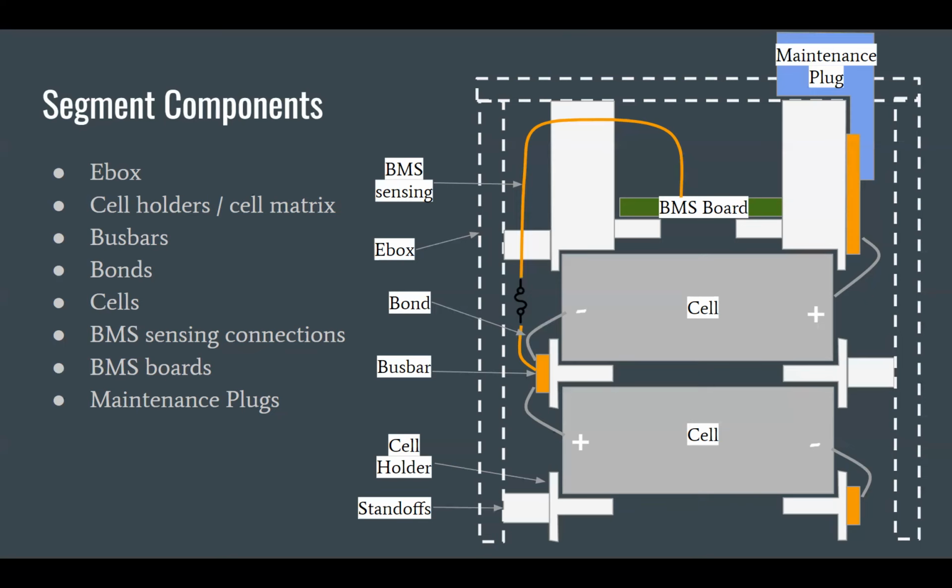Why are they not symmetrical? Like, why is this taller than that? I feel like it'd be symmetrical. I think it's because of the way that the voltage zigzags through, it has to go across the bottom. And so we have a big thick bus bar across the bottom on the side that's taller. If you look here at the bottom, you see one long silver strip at the bottom of this. But on the other side, we do not have one, just because of how the voltages in the directions of the cells work. You only need that on one side.